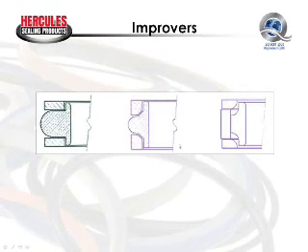Here we see what's called a wide-base T-seal. Wide-base T-seal was developed to replace an O-ring and two backup rings, which are used in double-acting applications. This seal also retains the round sealing lip like the O-ring, but it has a flat base, which gives much greater stability to the seal, and it has the backup rings built into it as an O-ring and two backup rings. The advantage here is the flat base, which gives a lot more stability to the seal in the seal groove.